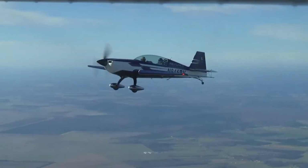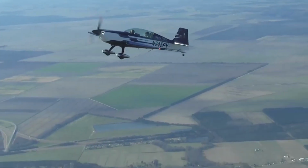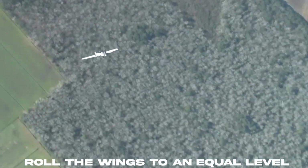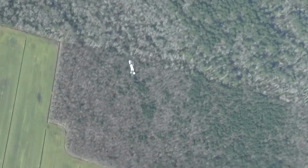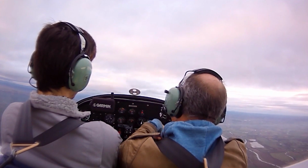Normally, recovering from a stall is not so complicated. There are 2 things that the pilot must do. 1. Push the nose of the plane down. 2. Roll the wings to an equal level. The combined effort of these 2 actions causes a plane to recover from a stall. Once the plane has recovered, the previous altitude and path can be reobtained quite easily.